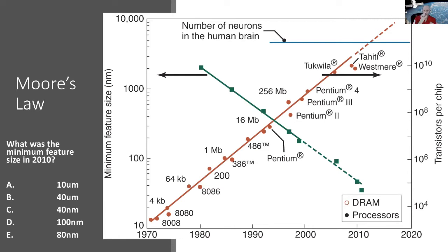If you're down to very small signals of a few electrons rather than thousands of electrons, there's a probability that electron can jump from one place to another through quantum effects. And that probability gets higher as you get closer and closer together. And you can also get tunneling through the p-n junction, right? If the channel on the gate gets too small, you can have the electron jump across.